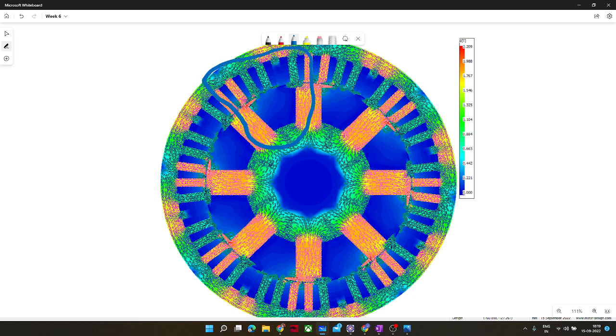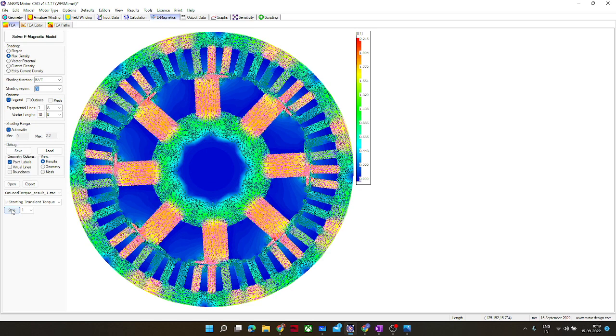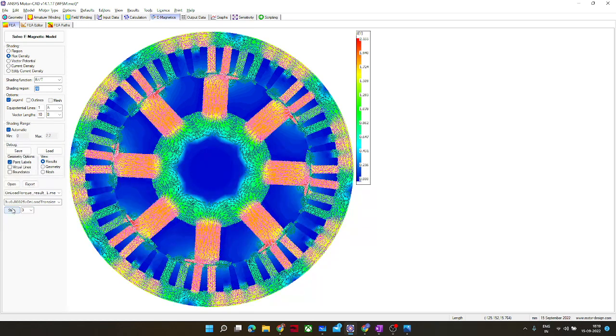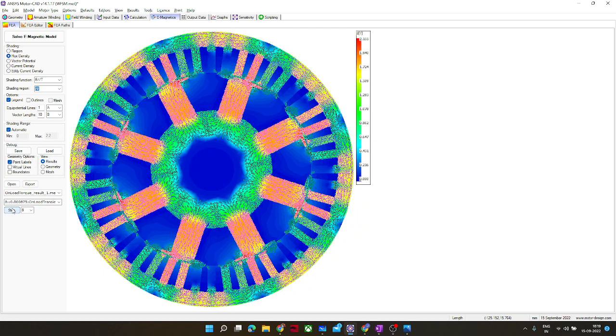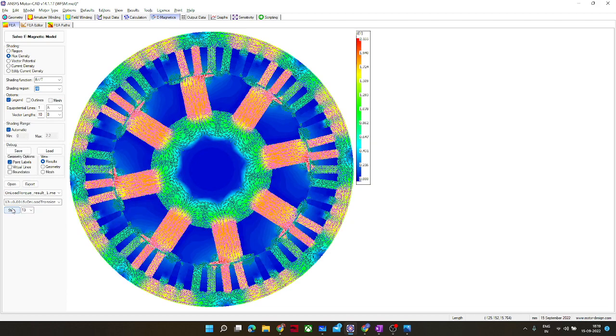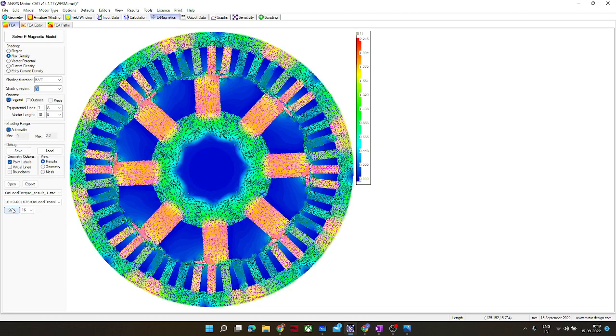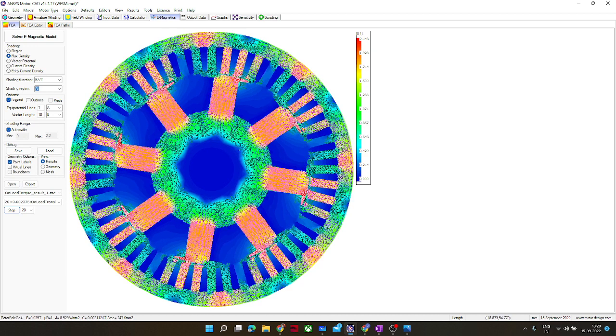And in similar fashion, the stator MMF will rotate and hence the rotor will rotate to catch up with the stator MMF. You see this animation? Here the stator MMF is rotating and the rotor is trying to catch the stator MMF through the minimum reluctance path. So this will be your D axis and this will be the Q axis.